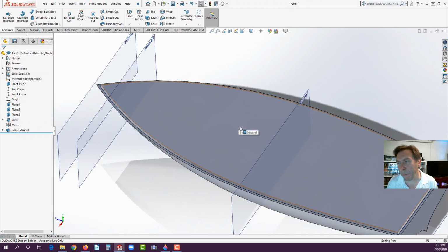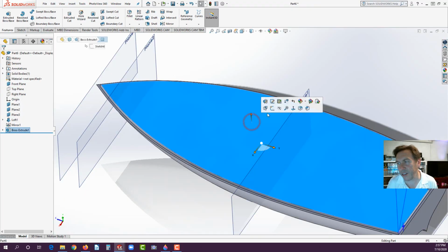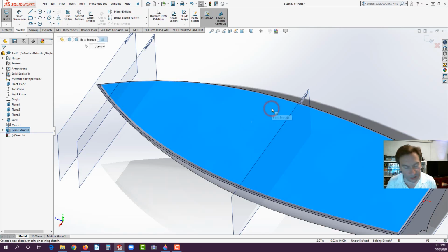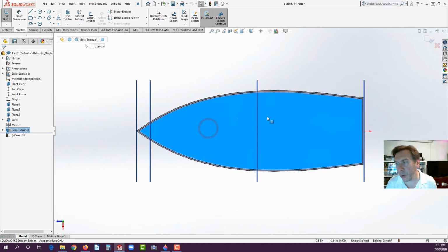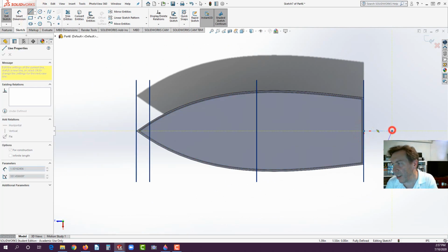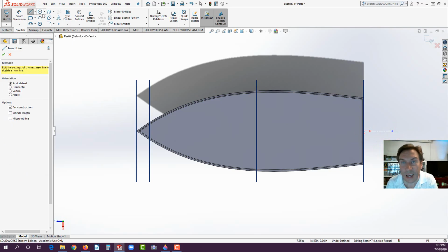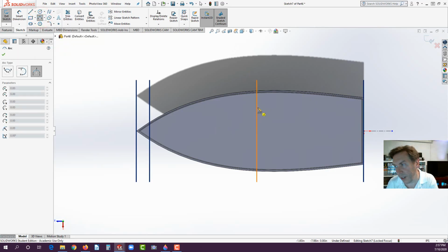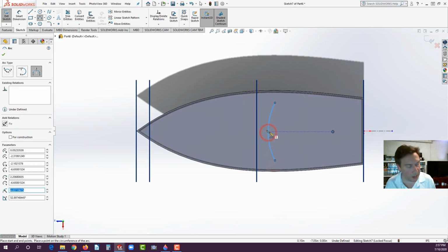Now let's go ahead and select this face here. Start a sketch. We go to the top view orientation. Since it's symmetric, I would recommend drawing a center line right at the origin. And I'm going to go over here to the 3-point arc. And I want to make that cockpit dart out a little bit. So I'm just eyeballing it right back here. Let's see. It has a very long, elongated front. I'm going to drag this out and get just a slight bow on it.